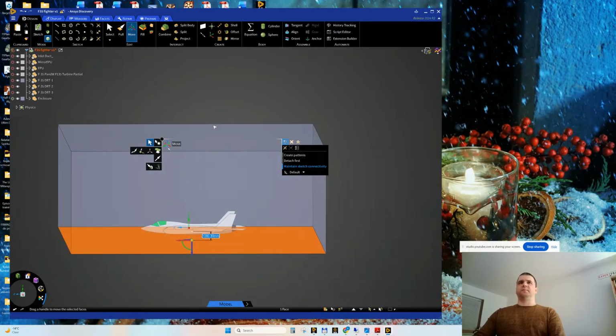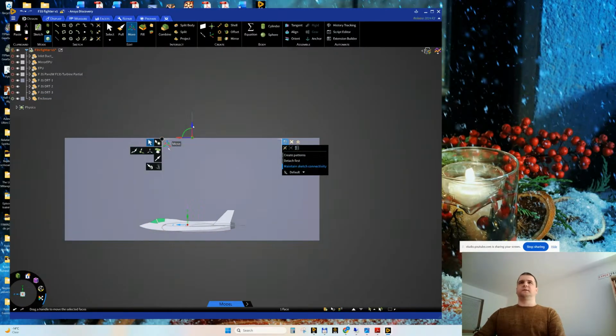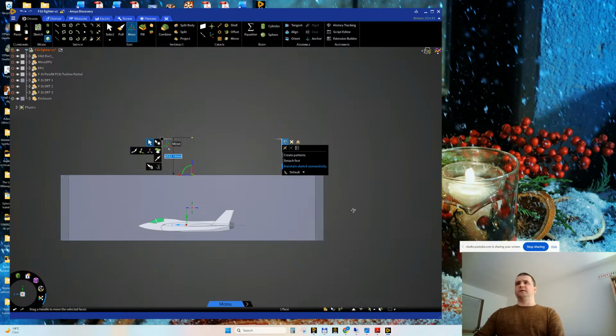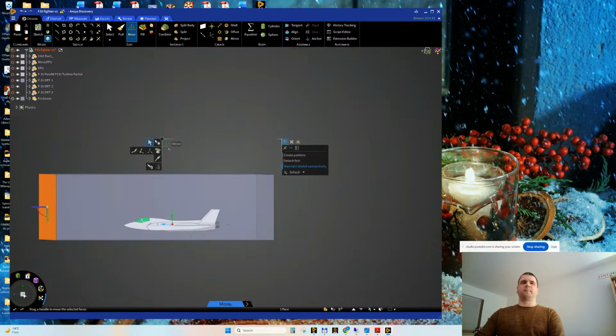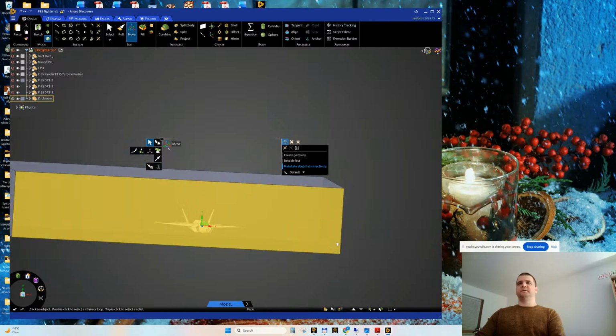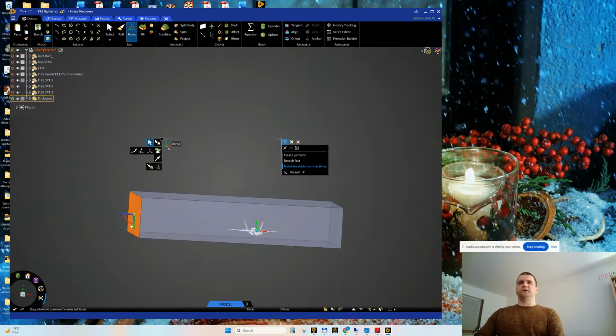And, for example, above, it's too much space, yeah? It's a waste of mesh. Here, we don't care too much, so let's also resize it. Also here. Something like this. How much space do we leave here? It's kind of too much for the outlet.